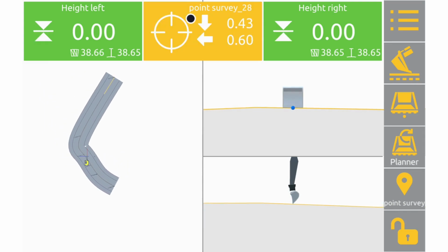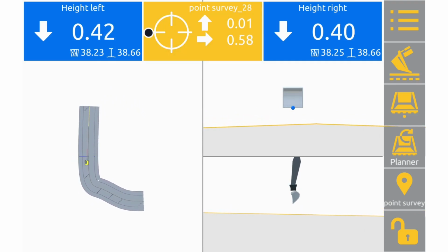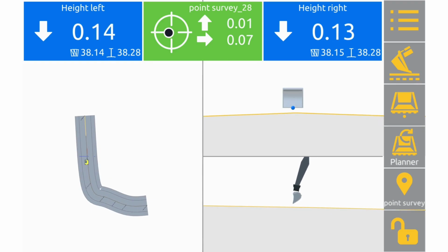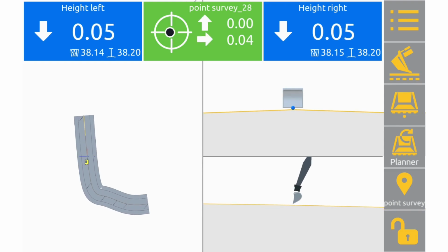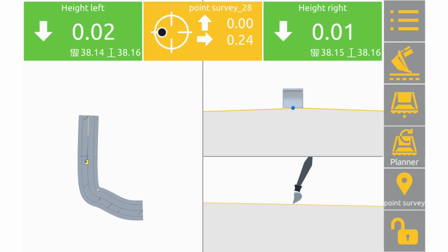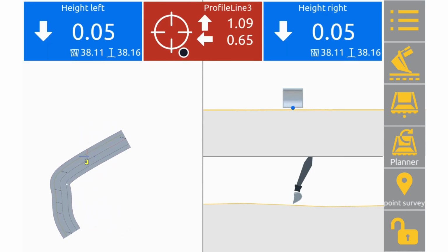Basically you can work from one polyline to create a surface drawing of a road. And if you look at the top screen on the right, you can see when I put my excavator bucket on the target, if I move out from it, you can see the camber there. The bucket is lifting away.